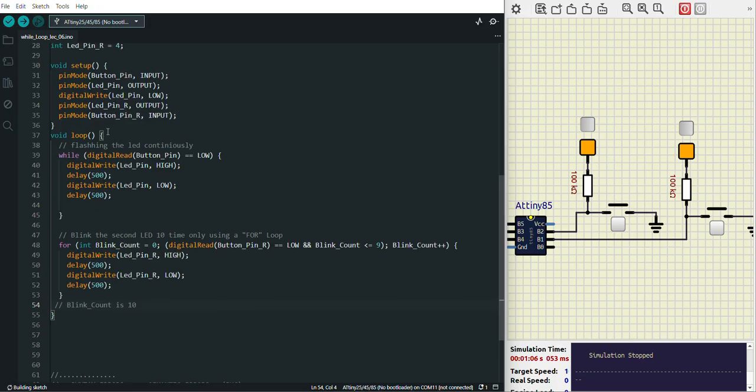So now we get back because the loop is done. The void loop is done. We have to go back to the top of the loop. Then we check for this. If you've not pressed it, it's not going to do anything. Now it comes back. Here is the problem now. Here is the trouble causer. This keeps on initializing. It's like a reset.